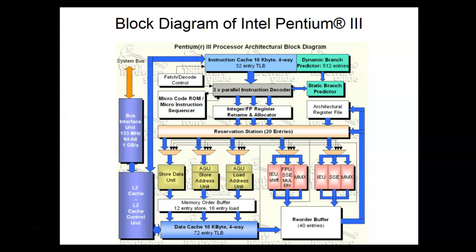Normally it runs a little power on self-test, which we can't see anymore. We can see it on our PLC because when you first turn it on, you saw the lights start blinking, so it's doing a little self-test to make sure it's capable of running and there's no faults. On one of them the red light stayed on, right?